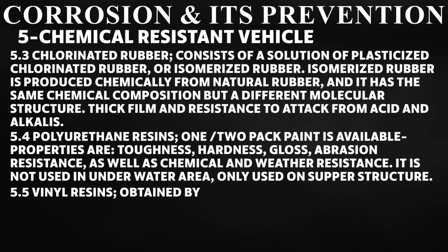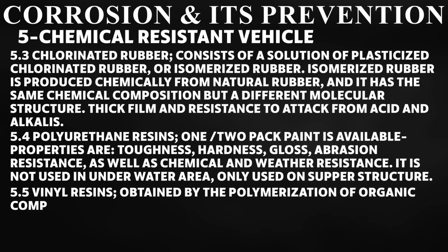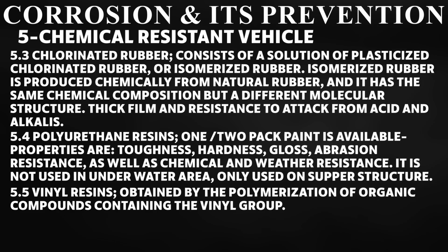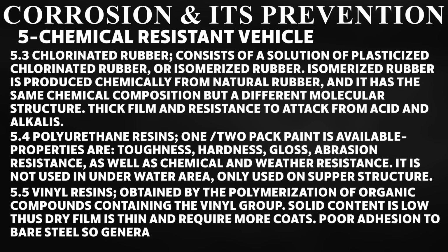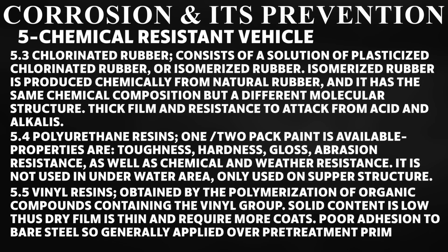5.5 Vinyl resins, obtained by the polymerization of organic compounds containing the vinyl group. Solid content is low, thus the dry film is thin and requires more coats. Poor adhesion to bare steel, so generally applied over a pretreatment primer. It is effective for underwater protection of steel.